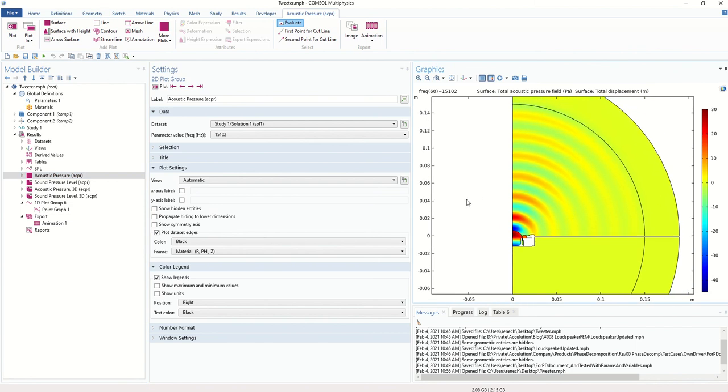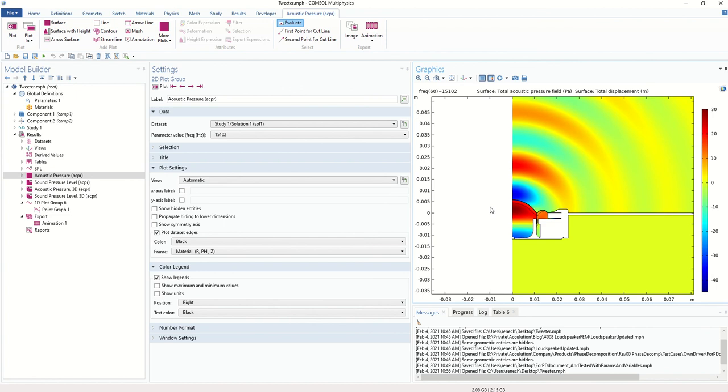And again, you can do the same thing for the woofer and see the resulting sound pressure level from the woofer on its own. And if you want to, you can apply a crossover if you know the transfer function. You can apply the crossover as an active one, so you just multiply a known, let's say, Linkwitz-Riley second order transfer function upon the initial voltage input. So you've already compensated for that crossover.